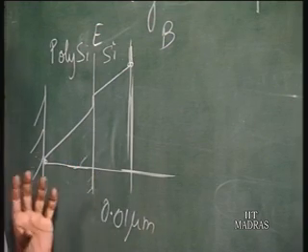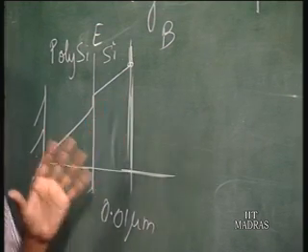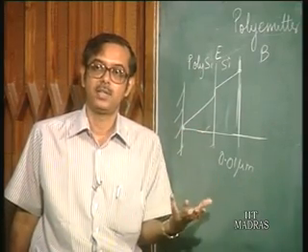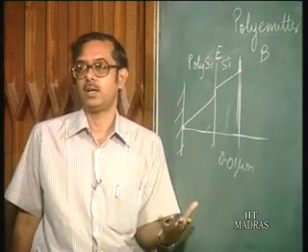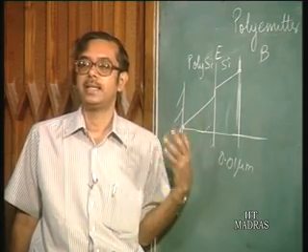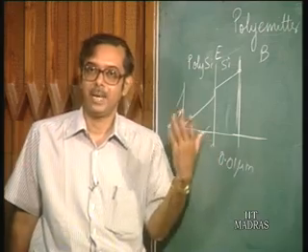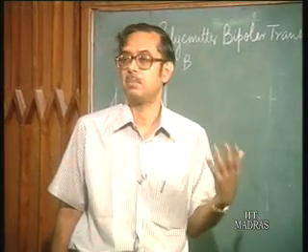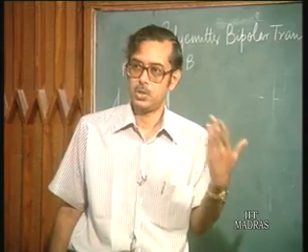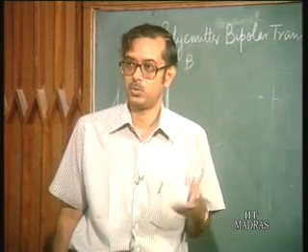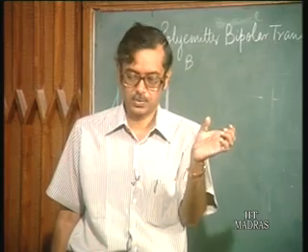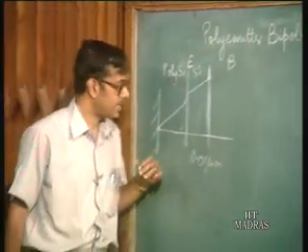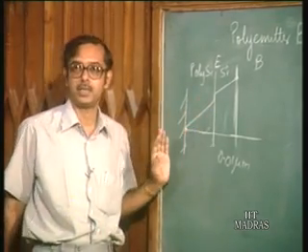And again, because you can have a large WE by WB ratio, you can trade it off with the doping concentration ratio, and in fact you can also increase the base doping concentration, which has other effects like reducing the base resistance, which is advantageous from the circuit point of view, because the base time constant to charge the base would be reduced. So, these are the advantages of a polyemitter transistor.